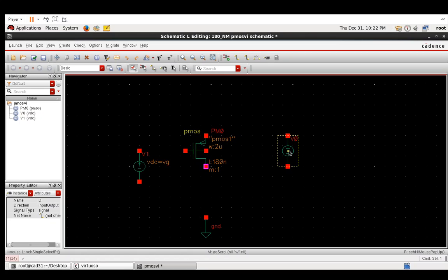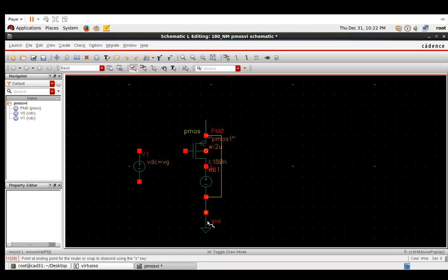What we are going to do is put this voltage source here. Okay, and I will put this to ground, or I'll just separate this a little bit for now. And what I'm going to do is connect the source terminal, okay, permanently to ground. You see this thing here, the source terminal is permanently connected to ground. So now suppose I put some value here. Okay, VD, for example, if it is 2 volts, then VDS will become 2 minus 0, which is plus 2 volts. So I don't want that, right? I want only negative values for VDS, and the same thing for VGS also.